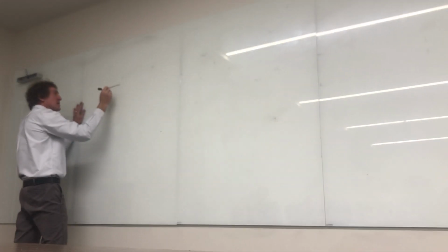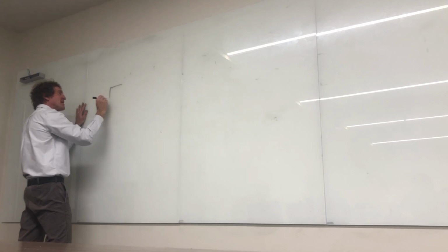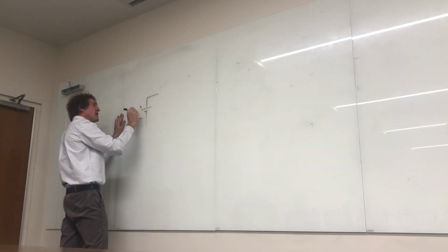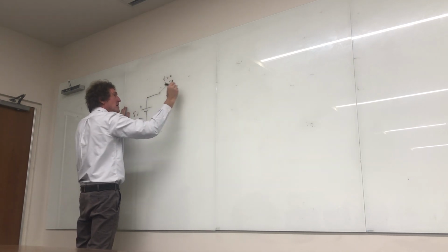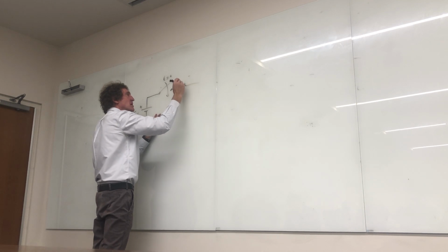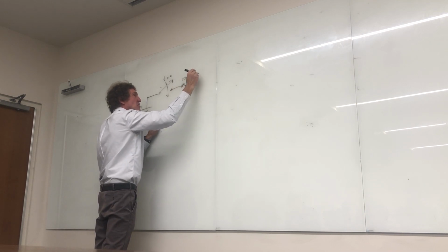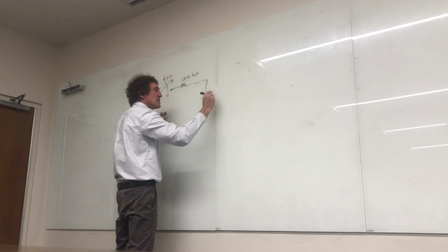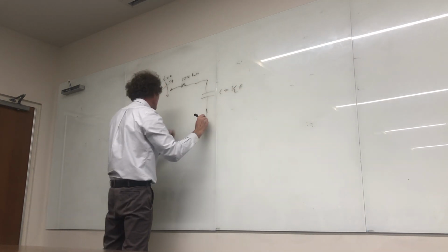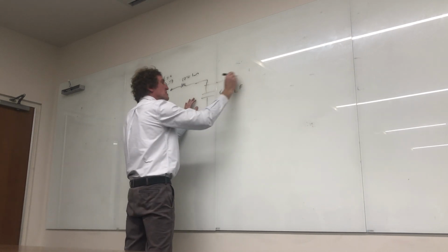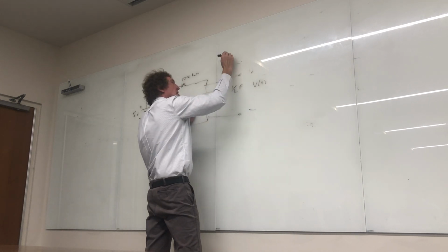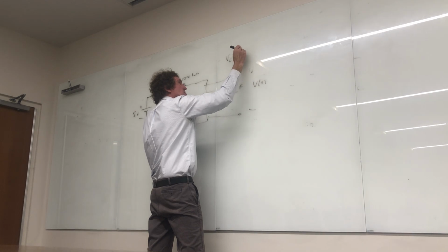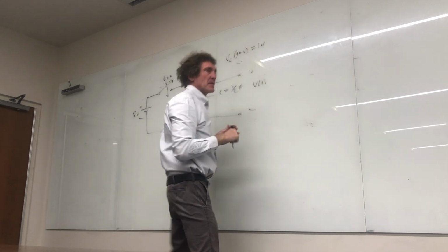So for this one, I'm going to put plus or minus 5 volts there. This is like a Dave Irwin problem. Got a switch that's going to flip it to equal 0. Then I'm going to put a resistor R, make it, say, 1 ohm, and a capacitor C, make it 1/2 farad. And I want the voltage across this capacitor, so I want plus to minus V of t. But I'm going to say VC, the voltage on the capacitor at t equals 0, is going to be 1 volt. All right?